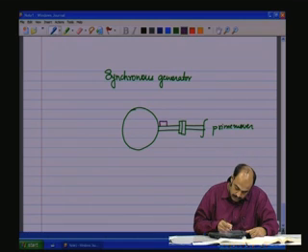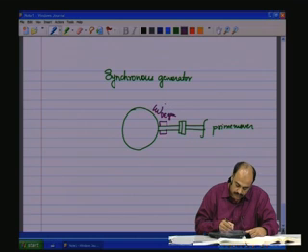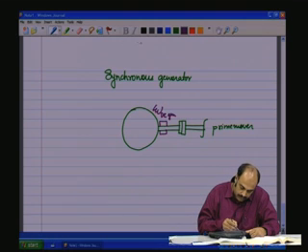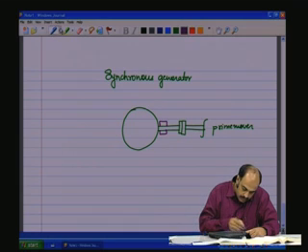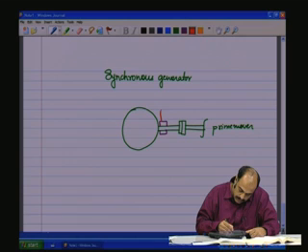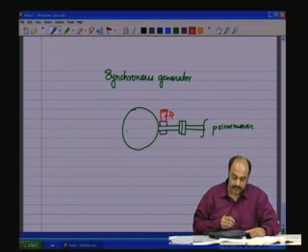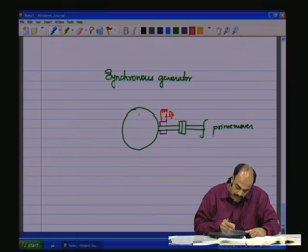of course the DC gen. So DC gen is going to give the excitation for the rotor coils. So this is IF. Let me make some space here. So the DC generator is going to produce IF, which is going to energize the rotor inside, and that is the rotor.